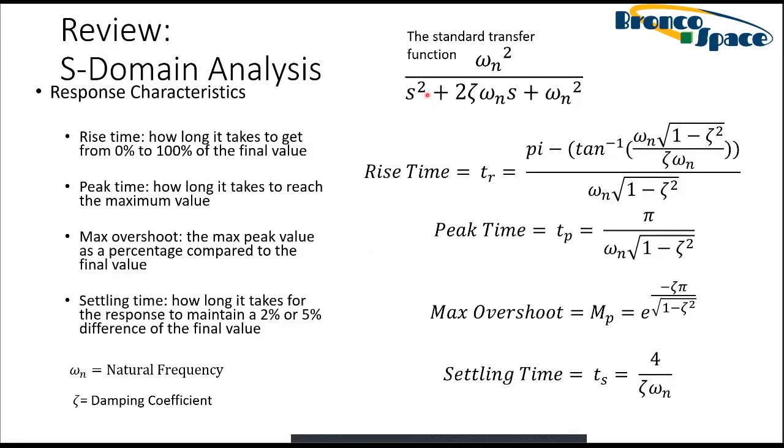And something called a transfer function goes in between them. The transfer function is like, you put in X at one end, and what you get out the other end is the output. X is your input. And the transfer function, with this fancy math, can roughly idealize how the system is going to respond in terms of rise time, like how long it takes to get to the value you wanted, peak time, like how long to get to a maximum value. Because sometimes you can have things like overshoot, undershoot, and how long does it take to settle.